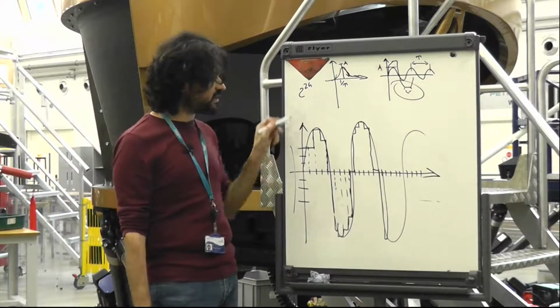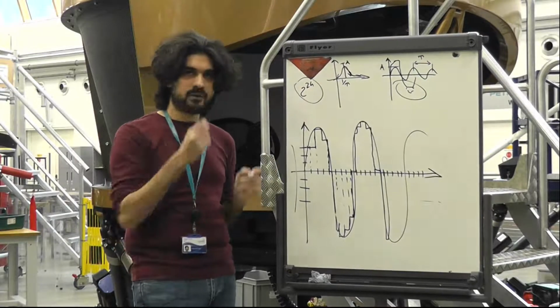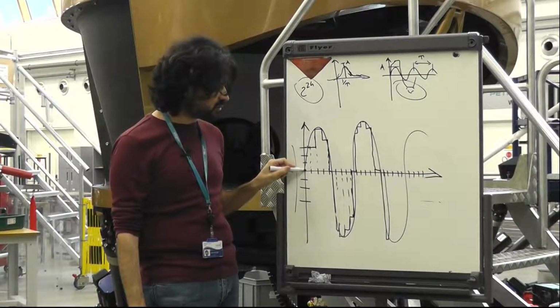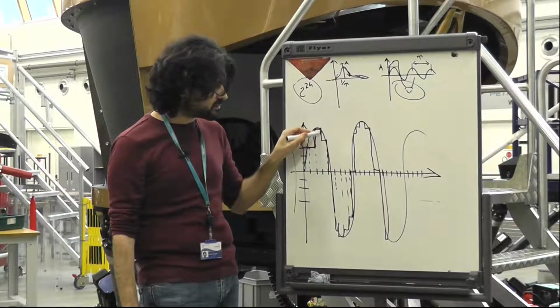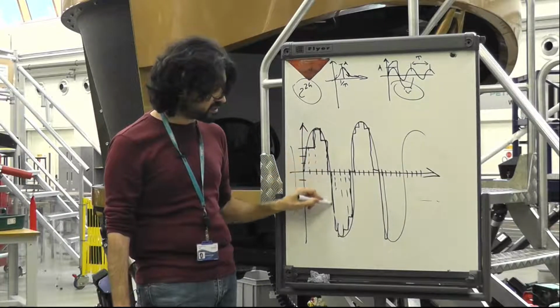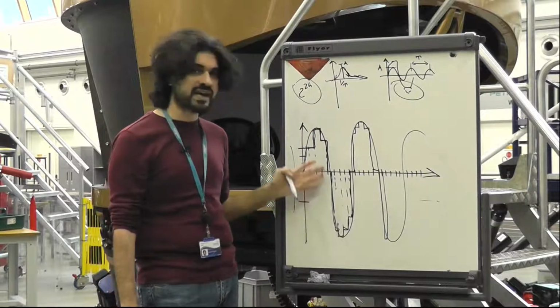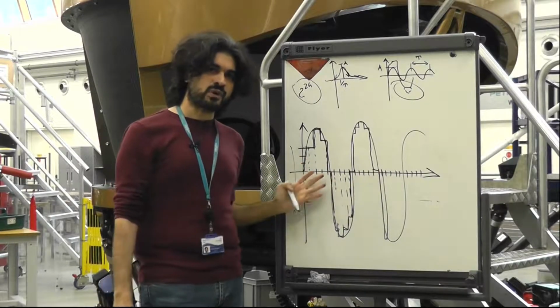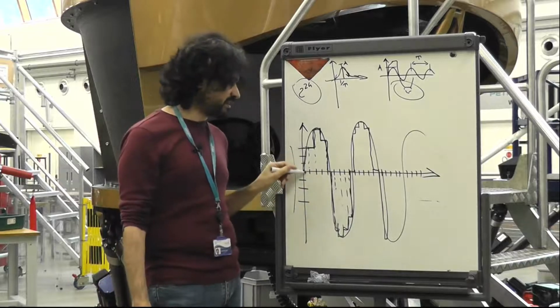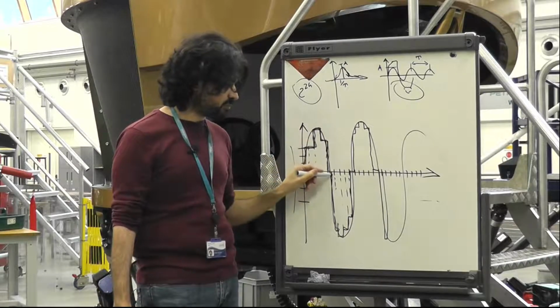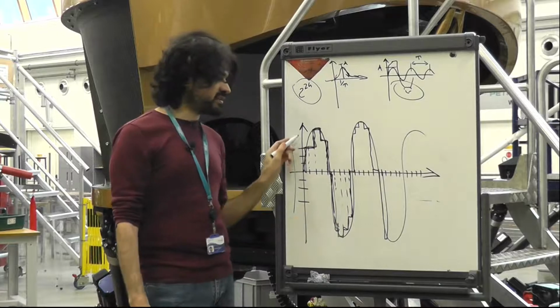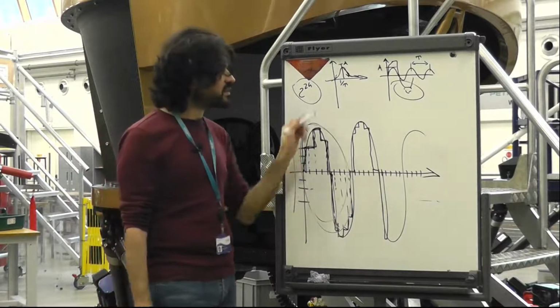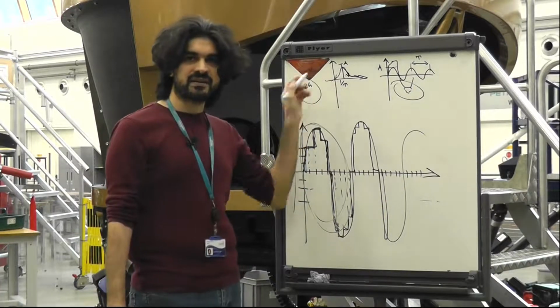If you use 7 out of these many, your signal will look like a set of steps. So this is a blocky signal. Your analog sine wave will be captured digitally with this horrible set of steps, and if you do the FFT of this, you'll get something bad as well.